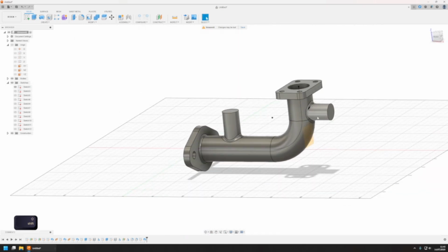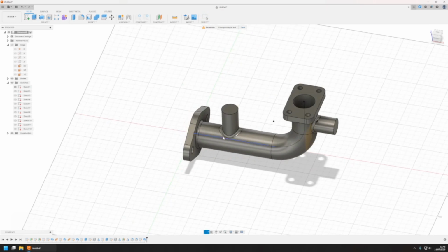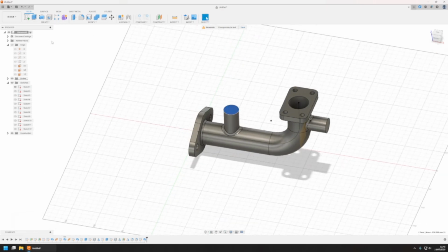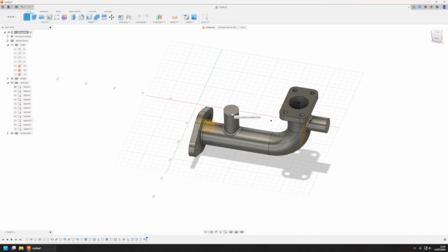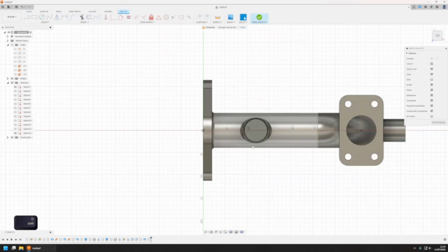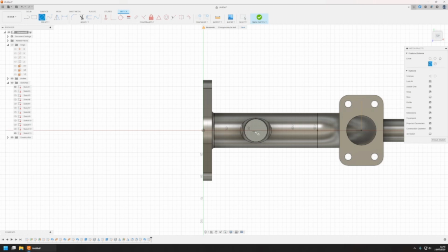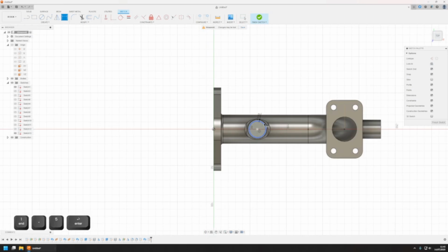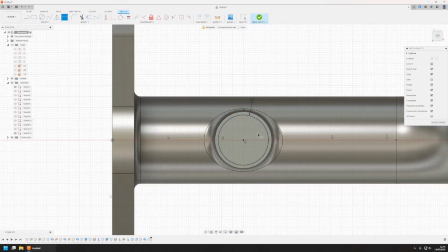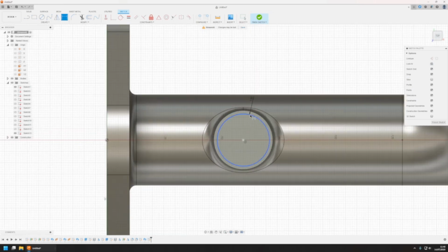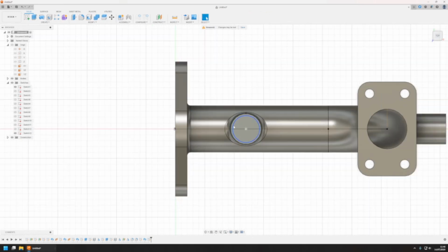Now to join the two cuts, all the cuts together, we just need to do this exact same thing here. Now we can select this one because it's going to be perpendicular to this anyway. You can snap it like this. See, it's gonna snap to the circle. Here you can actually put the dimension like this and select the thickness actually, not the exact circle. You don't need to put the exact diameter, you can do it like this to control the wall thickness. Finish the sketch.